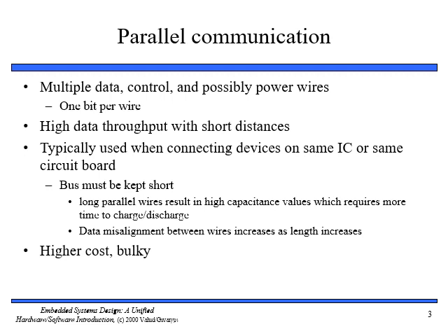Such misalignment of data becomes more of a problem as the length of the parallel bus increases. Another problem with parallel buses is that they are more costly to construct, as I've told you, and this will make them bulky, especially when considering the insulation that must be used to prevent the noise from each wire from interfering with the other wires.